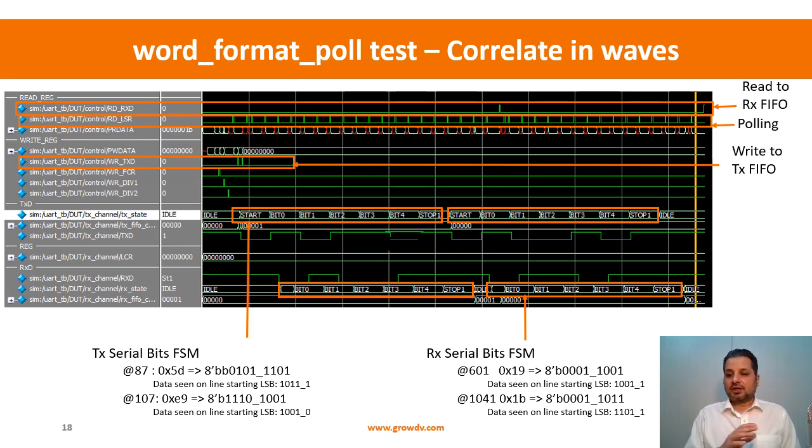Not especially for a test that has run for a longer duration of time. If it has failed immediately after reset or the first transaction, then that is fine. There might be a very basic issue, so you can directly jump into the waveform and look at it. But if a test has run for a length and generated a lot of traffic, you should not directly be jumping into the waveforms. You have to remember that the first step is always to force yourself to look at the log file